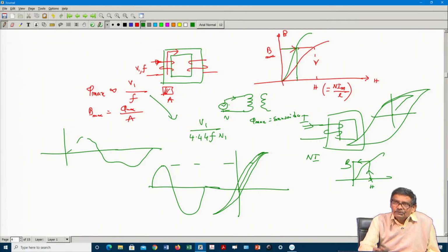So, if it supplies sinusoidal current, the other way around, that is, if a coil is excited by a single sinusoidal frequency current, then the flux in the core will not be fundamental 50 hertz alone. Induced voltage then will have a prominent third harmonic, and that induced voltage will then find a closed path here and will try to compensate for the third harmonic current which is necessary to make the flux more like sinusoidal. Got the point?